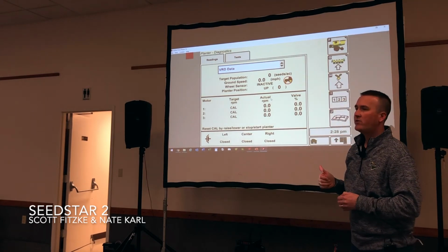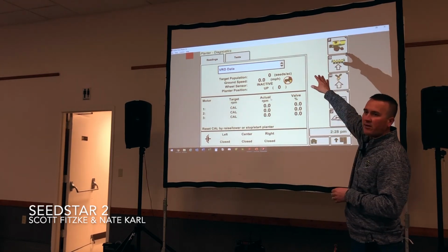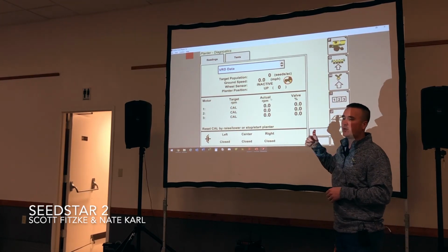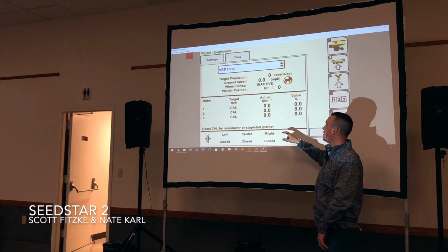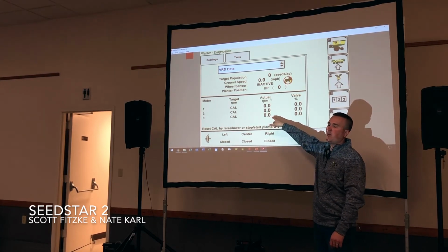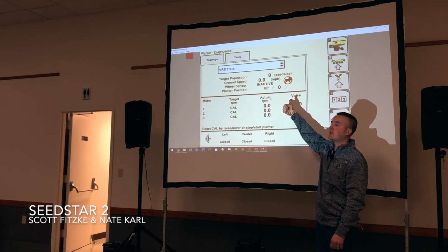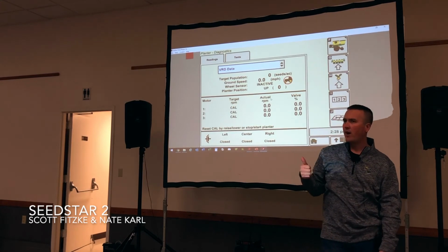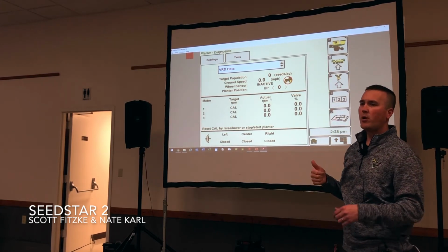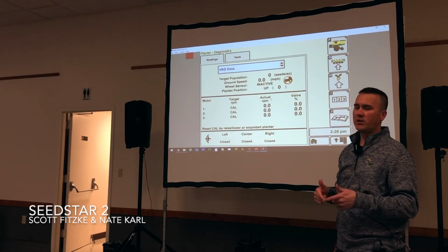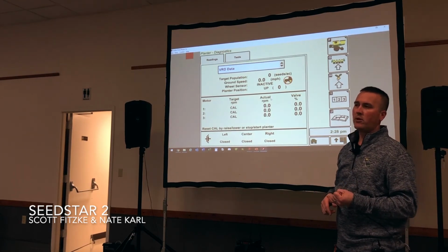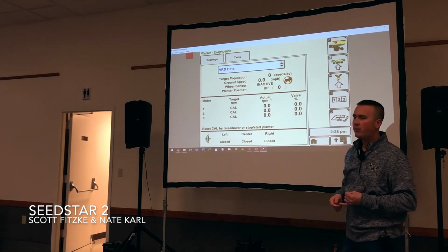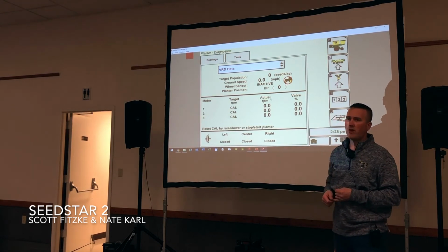So if I have a drive section that was hanging down on me and I saw it from that main run screen, I saw one was dragging down, I could come in here and diagnose a little bit further. And I could say, okay, if it was dragging down and I see it in here, yep, I'm turning less RPM, so that makes sense that my population is less. Now I come over here to look at my valve percentage, and maybe I'm pushing harder on that valve. So if I'm pushing harder on that motor to spin faster, and I'm not accomplishing that, I've got a problem. So either I have a mechanical problem, a bearing or something hanging, something in the meter that's hanging up on me, or I've got an issue with that motor or the valve.